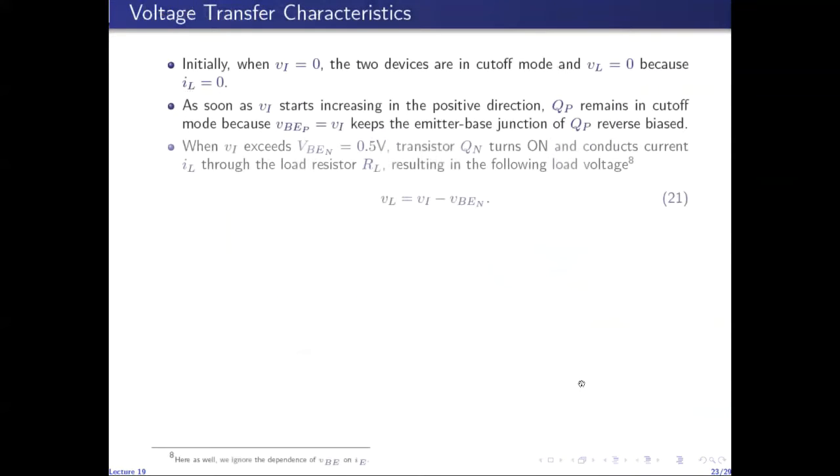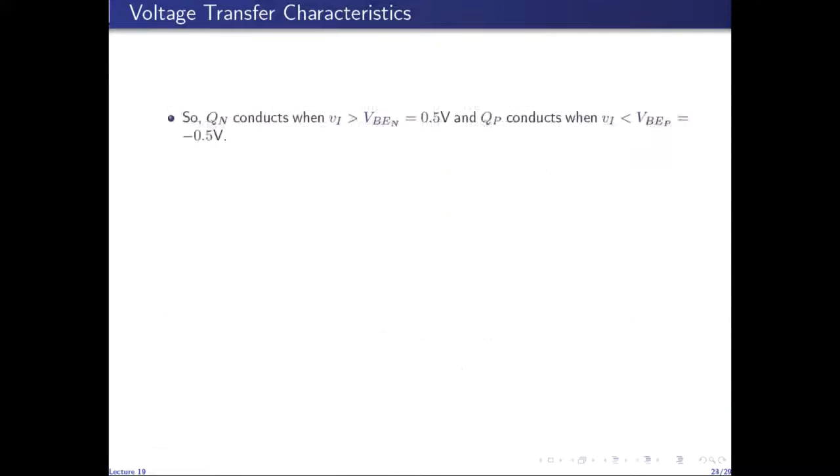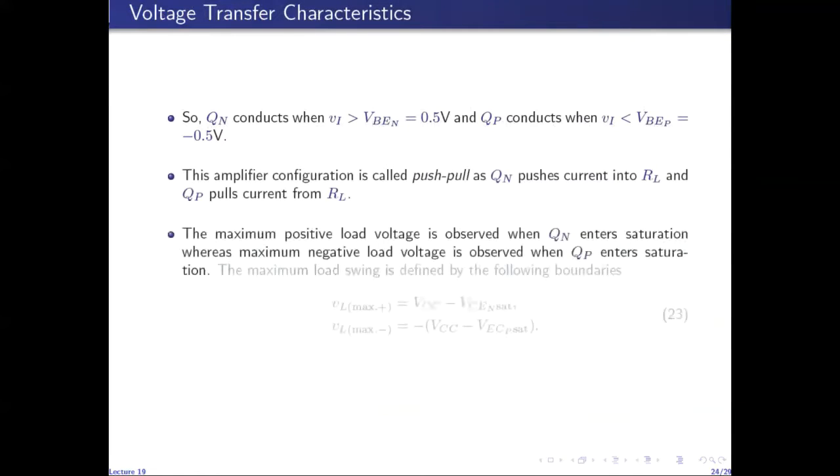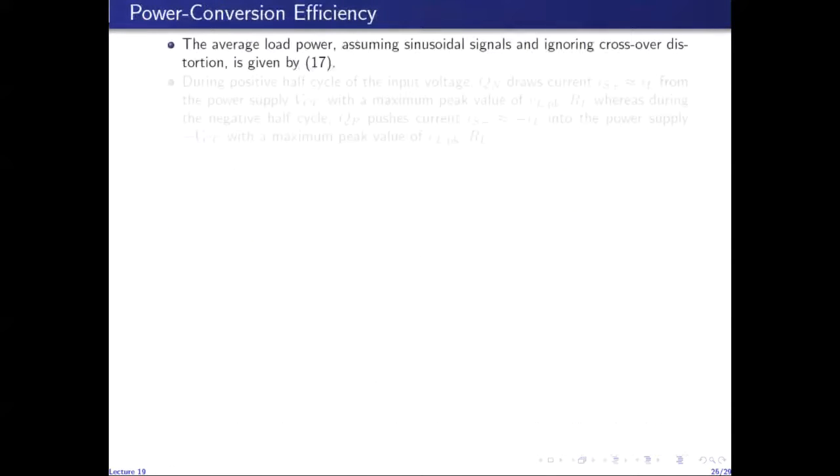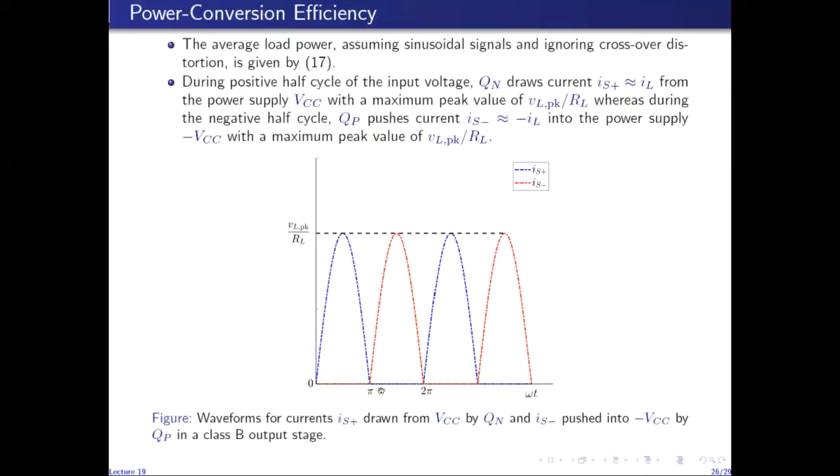So if I've drawn IS positive as swinging in the positive direction, then I must draw IS negative as swinging in the positive direction as well, because in the context of the circuit, they are both flowing from top to bottom, having the same direction. It's just that through the load, the current switches direction, but through the circuit, the direction of the current remains the same, which is why I've drawn this as swinging in the positive direction.